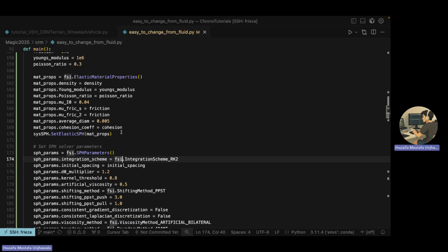Okay, so first the parameters are doubles, but the states are all floats. And we leave that to the user. In PyChrono you can't, but if you build Chrono from source and you enable the FSI module, you can choose whether to use double precision or single precision. In the code that I just ran, everything is single precision except the parameters.